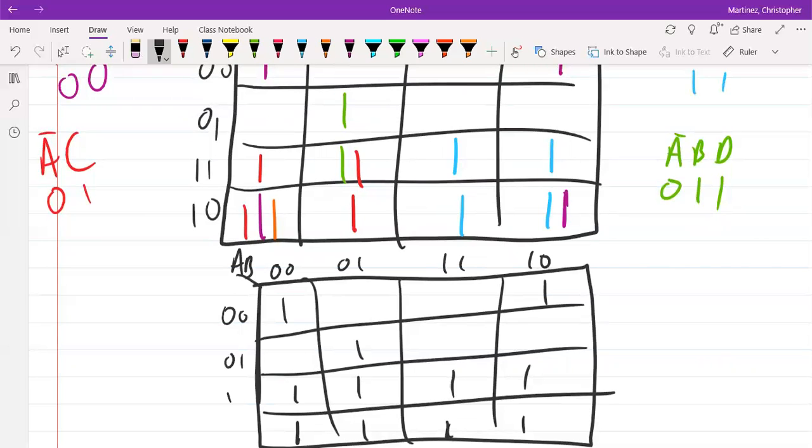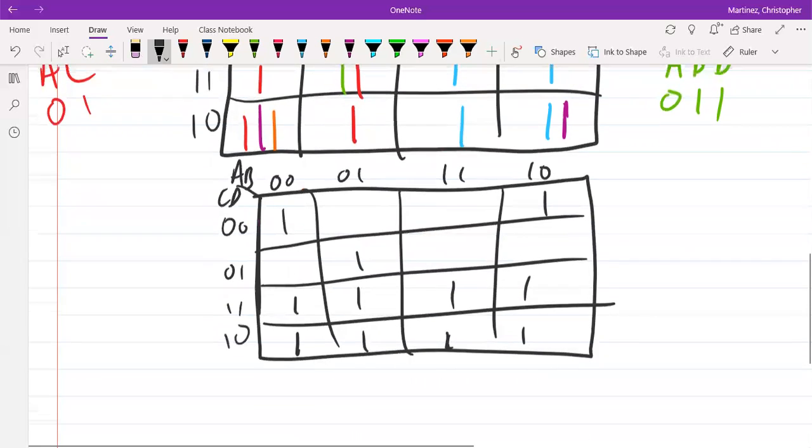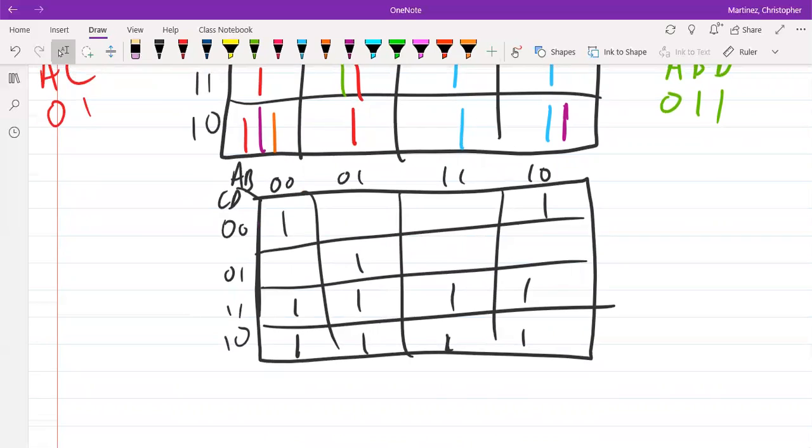these KMAPs. Now, the one thing you're going to have is when you have an expression, you're going to use that expression to fill in the KMAP. There will not be any don't cares. Don't cares can only come if you are given the numbers saying, these are the locations of don't cares. All right, so that's about how we go about taking a Boolean expression and filling in a KMAP.